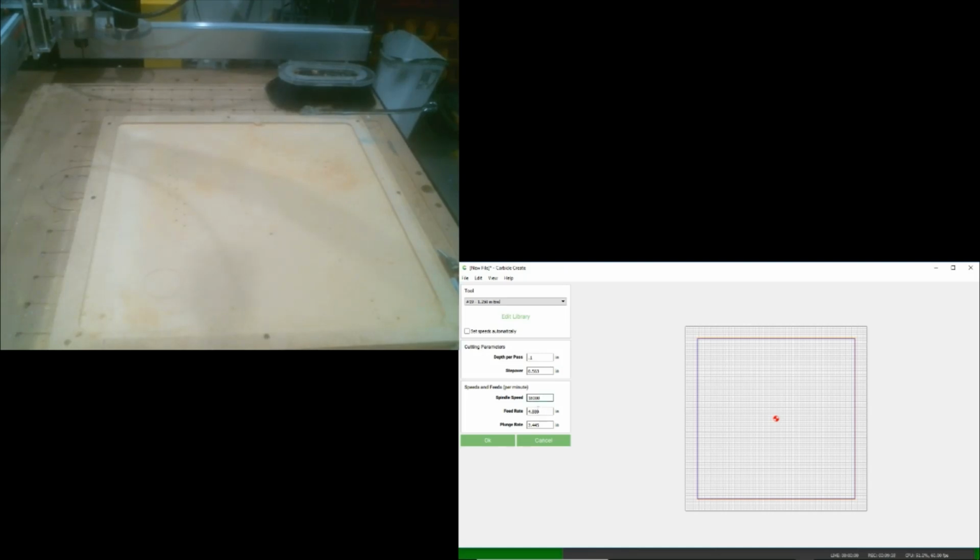It's a little fast for such a big bit, but I've run into that before, and we're fine. Just make sure it's tightened down and you call it good. Feed rate. At 4.8, it would probably take us hours to do this. 80 inches per minute, right? I know. If you're new, it seems fast. Trust me, your machine will handle it. So long as you keep that tight and you call it good, all will be well.